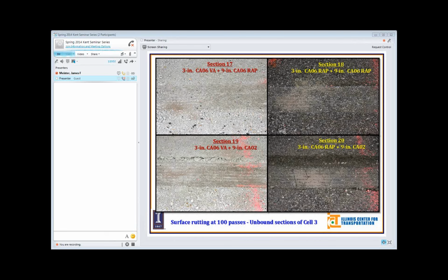Not the typical CA6 RAP you would find. That's one thing that we finally discovered, that what we see is more of the fractionated one with the coarse aggregate, coarse material mostly. If you think about RAP, and those of you working with RAP will know, in the finer parts of it you have higher binder. So actually we are looking at the less fine, more coarse aggregate side.